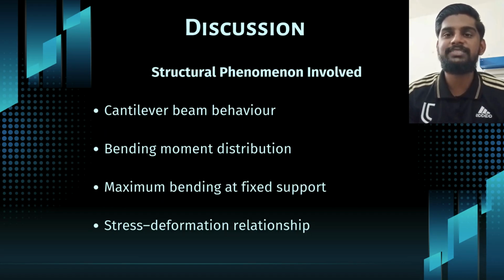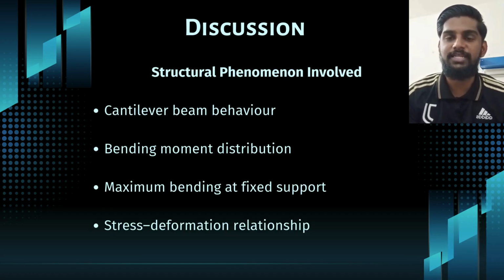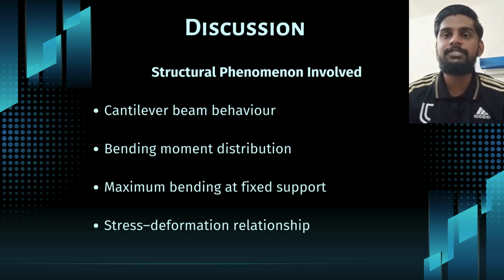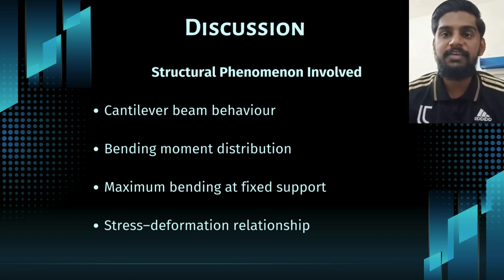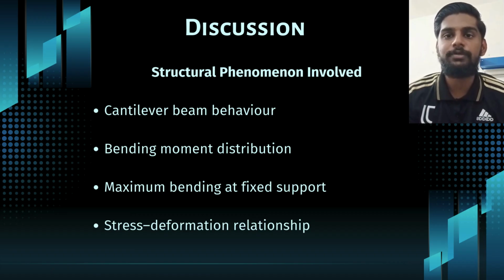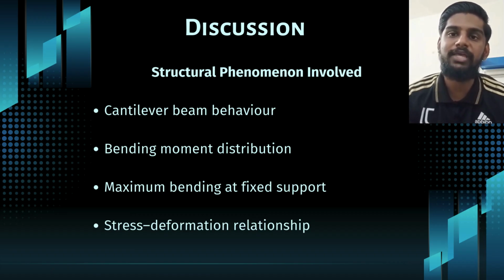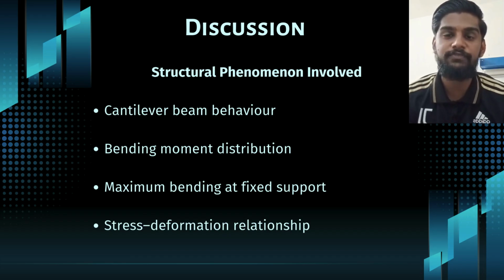Continuing, we see the structural phenomenon involved in this analysis. The wall-mounted PC monitor support arm behaves like a cantilever beam, where one end is fixed to the wall and the load is applied at the free end. Under this condition, the bending moment increases towards the fixed support, which explains why the higher stress is consistently observed near the wall plate region for all designs.